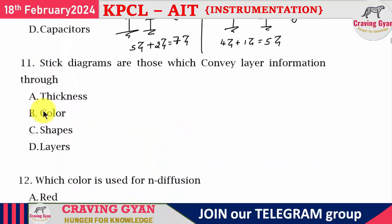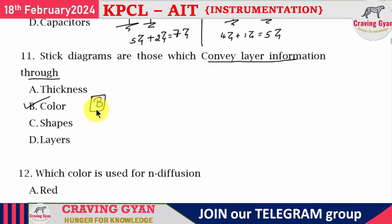11th question, you will be writing the schematic first, then the stick diagram, then later on you are getting into layout. Layout means actual distances, each and everything we are going to specify properly. The stick diagram is something like a cartoon kind of thing. The stick diagram is the one which conveys layer information, so it is going to provide information based on colors. Option B is going to follow.